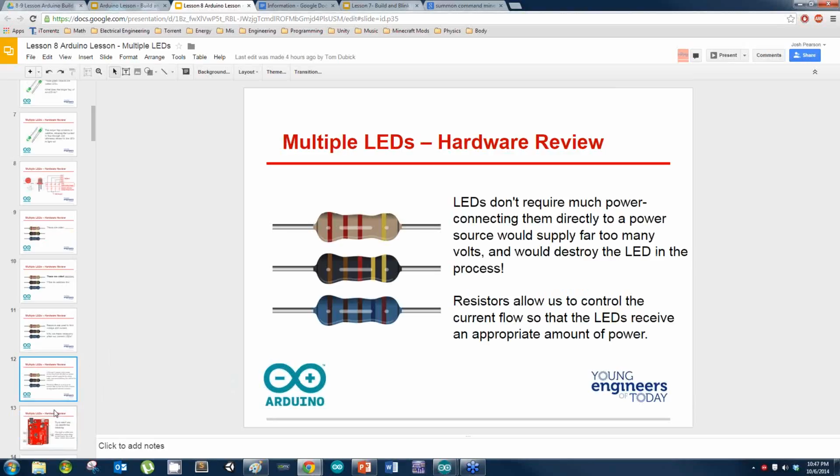The reason we put that resistor in there is because we are limiting both the voltage and the current that is able to go through it. By increasing the resistance, we are technically decreasing the current, but it's actually splitting the current. If you take that ground wire and hook it directly, don't do this, by the way, up to, say, A5, your LED will work, but it'll be really, really bright, and it will not work for a long time.